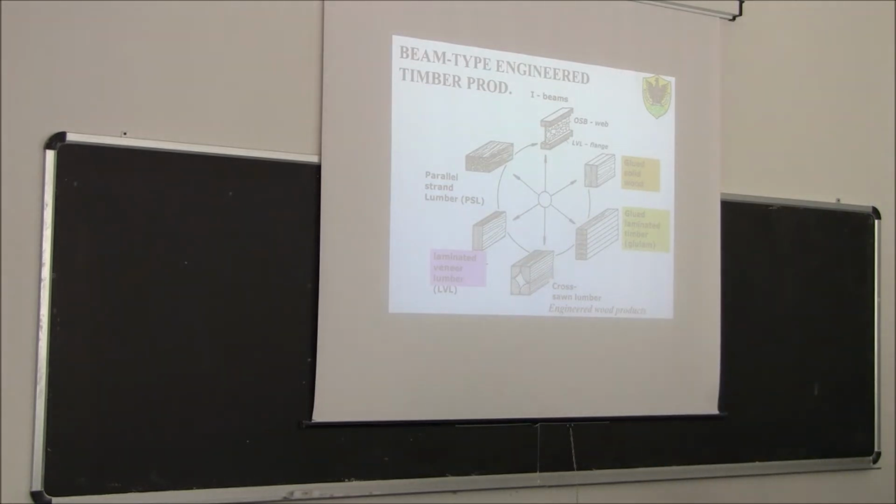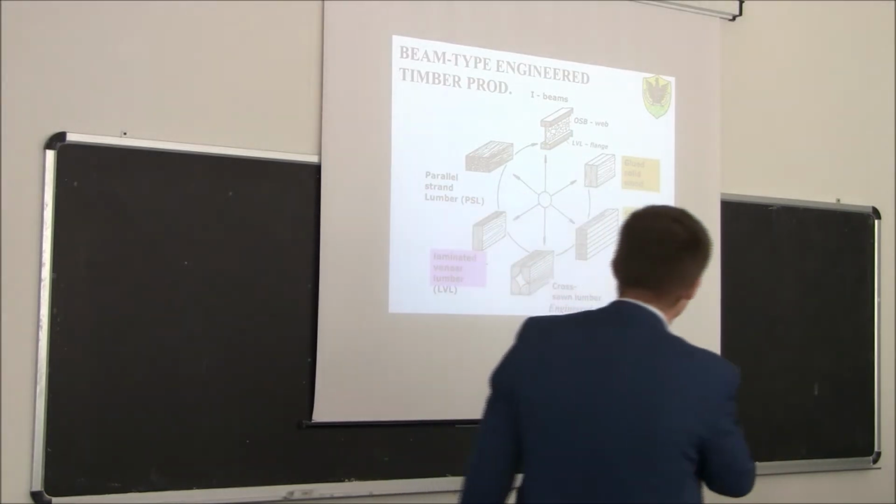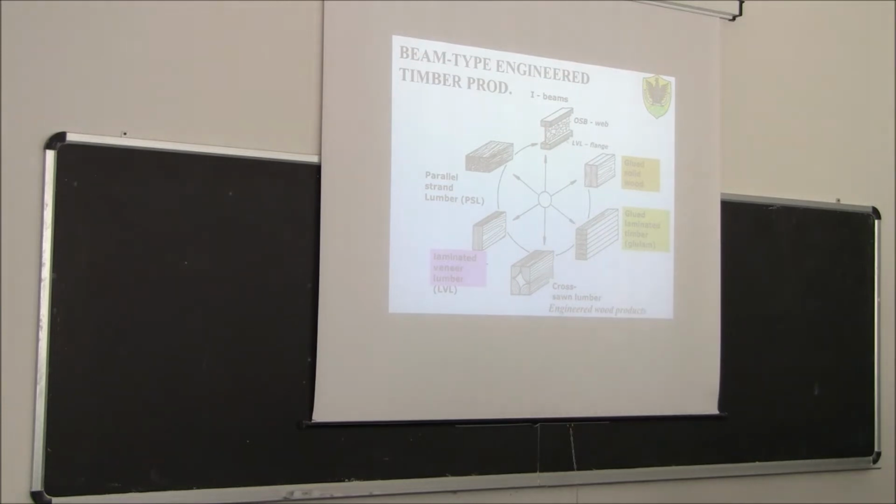In our country, for example, when we design a roof, not a roof for a house, so you don't need huge cross section. You could also use solid wood, some timber, but it's much more common to use this. Why? Because it's better to use this for small cross section. We're talking about, for example, 14 by 16, 20 by 30, quite small. Why is it more common to use this material? Because it's much more stable. The pieces of wood first are dried and are put together, the material is much more stable. You don't have problem with cracks and creep and so on.